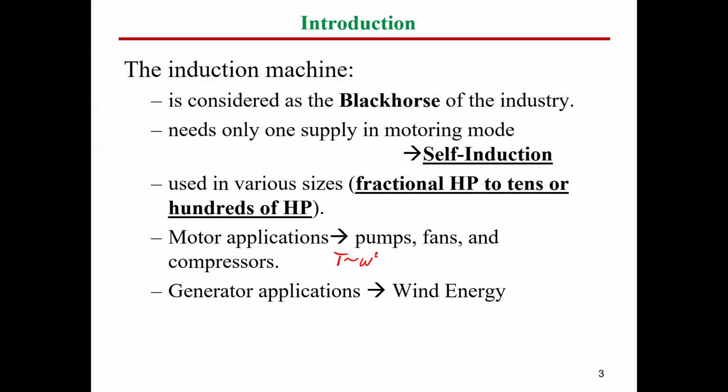Besides the induction motor, guys, we can find the induction generator used in wind energy applications. But for the induction generator, we cannot generate electricity by self-induction, because you have to have a source of field. We cannot convert mechanical power to electrical power without this source of field.